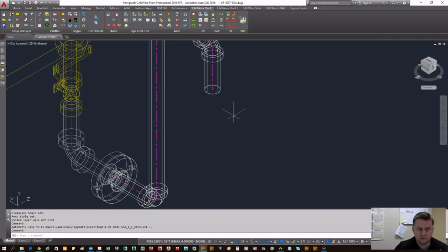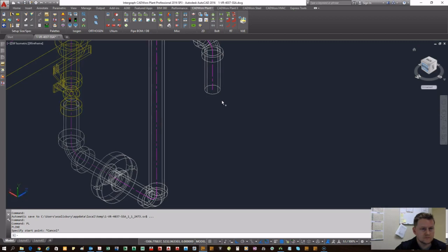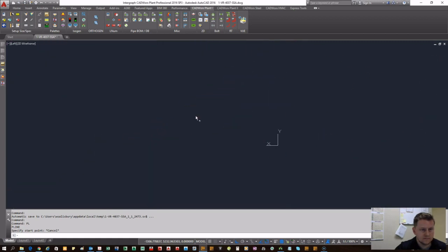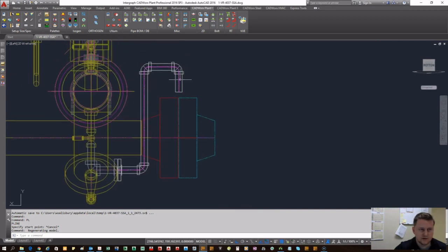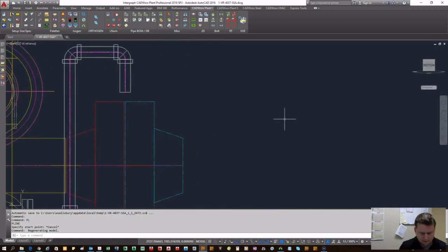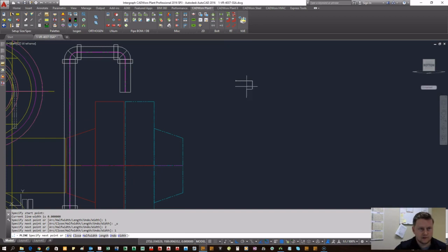First thing you want to do is build your 3D body. So we're going to go ahead and create something just like that. We'll switch to a 2D perspective, so we can see that same area that we're attaching to right here. You want to know your dimensions. Normally you can pull that from a cut sheet. So in this case, we're going to say 2 inches for the hub, 1 inch thick.